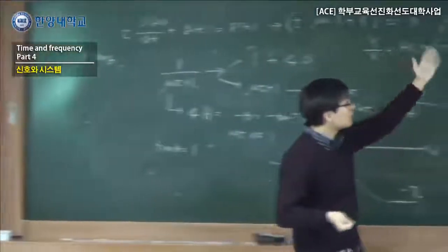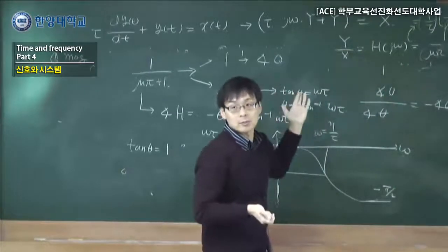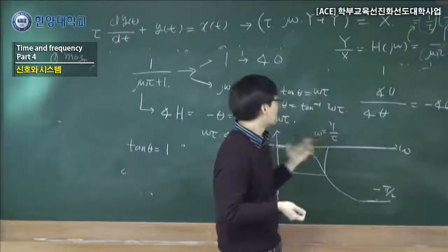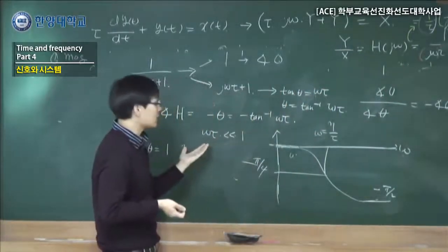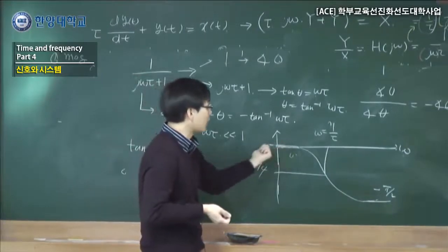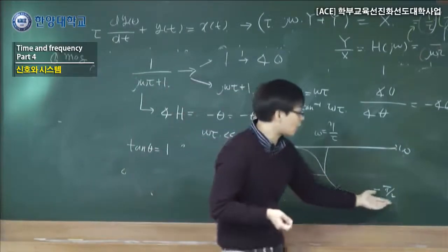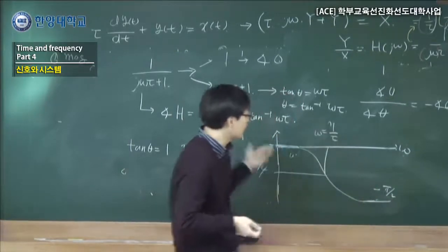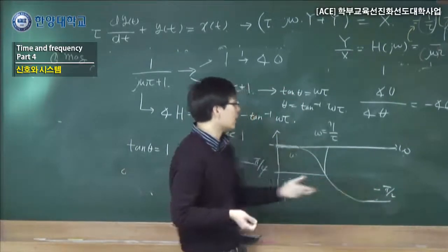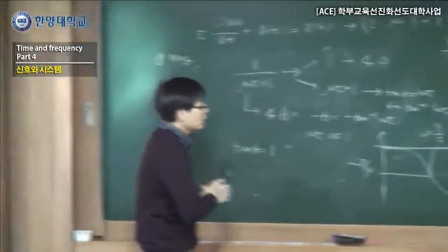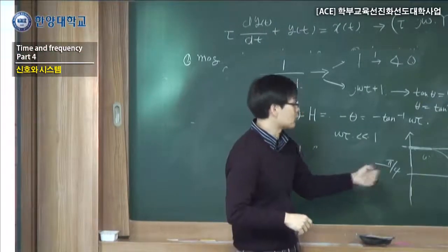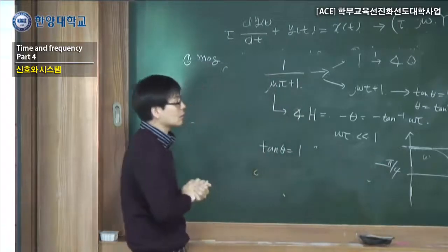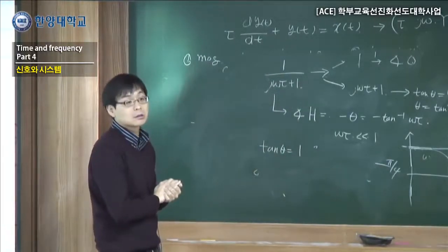We're starting from this one, coming from our impulse response, and say that we calculate our phase. When this one is very small, there will be 0. When this is very big, there will be half of pi, and there's a minus over here. At a certain point, it looks like that. That's the Bode plot.